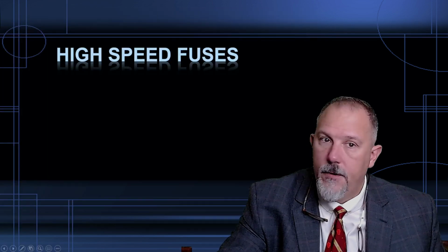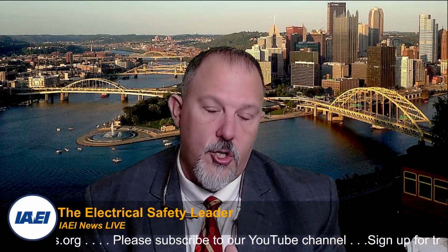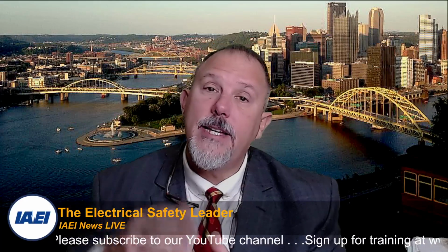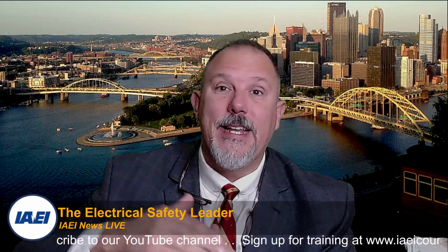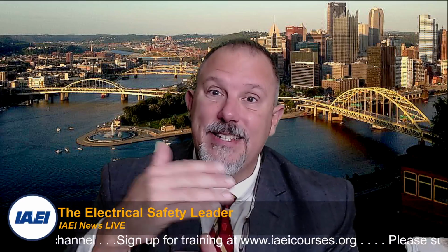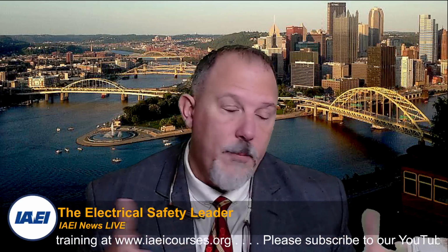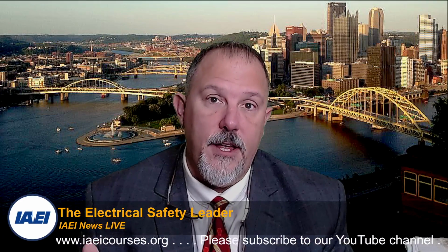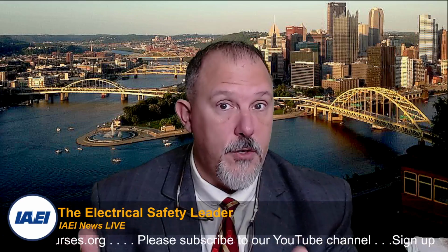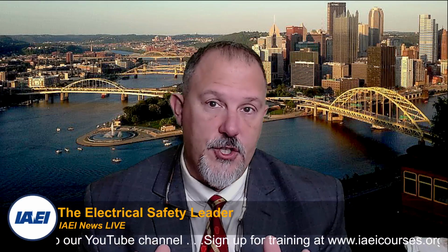So the interesting thing about fuses, when leveraged correctly, I can reduce the magnetic forces, which helps me get higher short circuit current ratings. I can reduce incident energy, which gives me a safer working environment. There's no better and more efficient device than a fuse to achieve those two goals, or none. I don't care what you bring to the table, nothing's going to operate as efficiently as a fuse on those high currents.